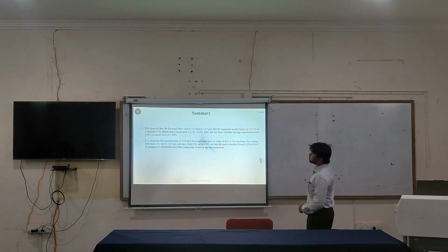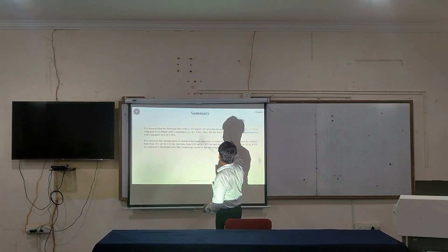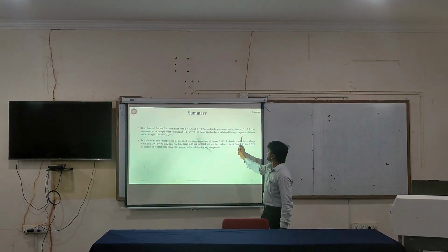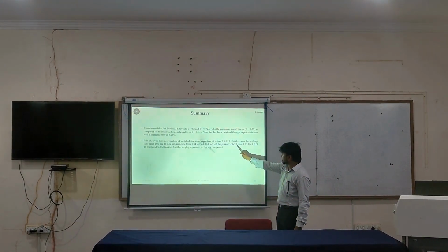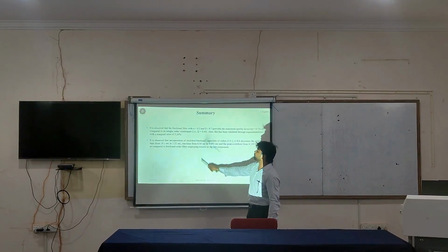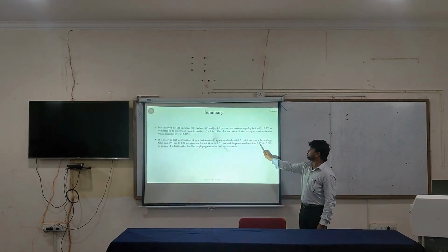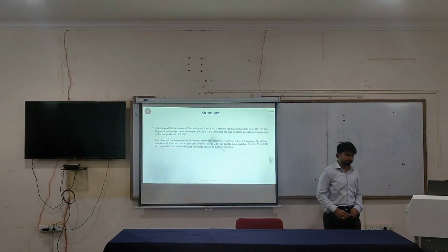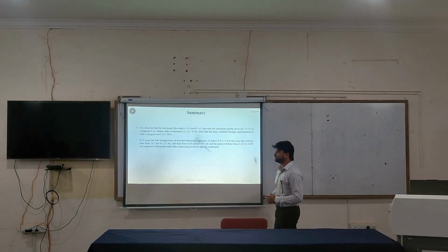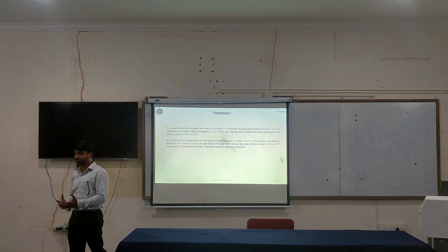Now coming on to the summary part, the orders were 0.3 and 0.7. The quality factor was 0.44, and here using switched fractional capacitors of orders 0.2 and 0.6 decreases the settling time from 19.1 seconds to 1.32 seconds, rise time from 0.54 seconds to 0.051 seconds, and peak overshoot from 0.133 to 0.019.